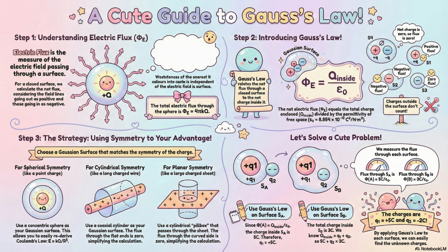They're loved for their high capacitance per volume, but they're hated for their volatility and limited lifespan. Aluminum electrolytics are polarized, and they have this built-in wear-out mechanism of electrolyte loss, or dry out. The liquid inside just evaporates over time. It slowly evaporates, especially when it gets hot. This is where that I²R heat from the ESR becomes a killer.